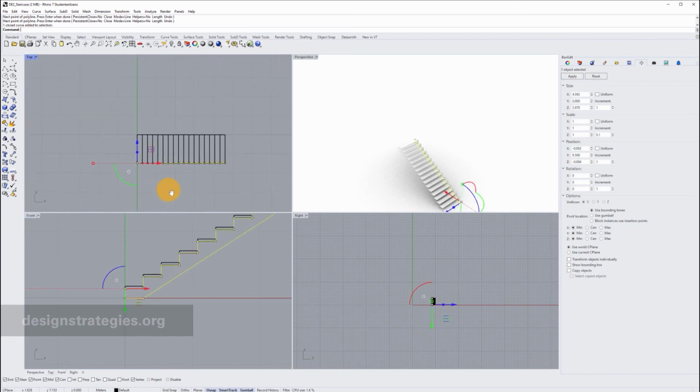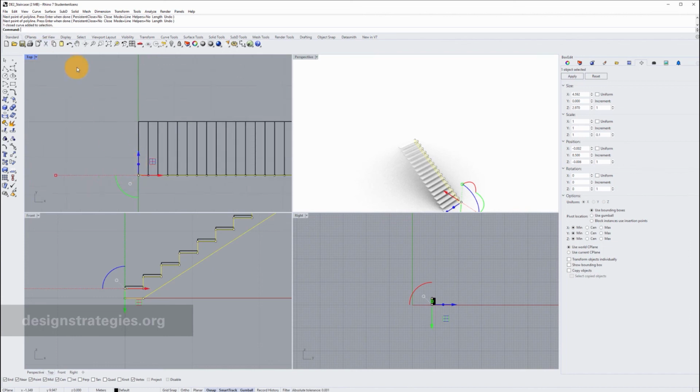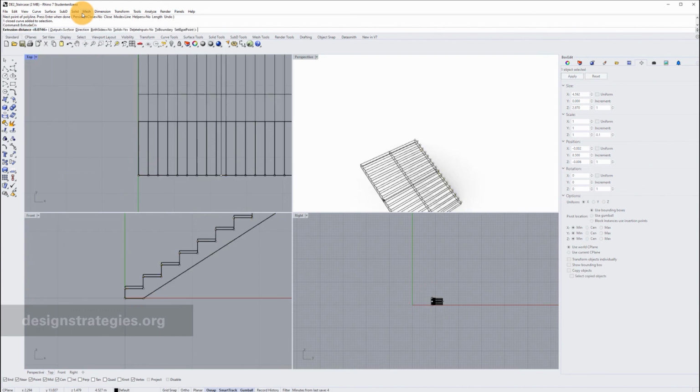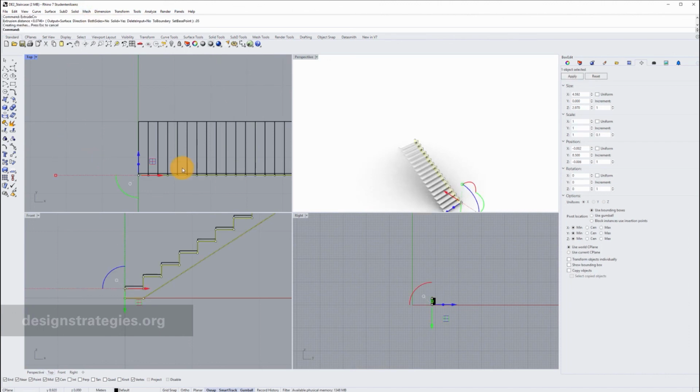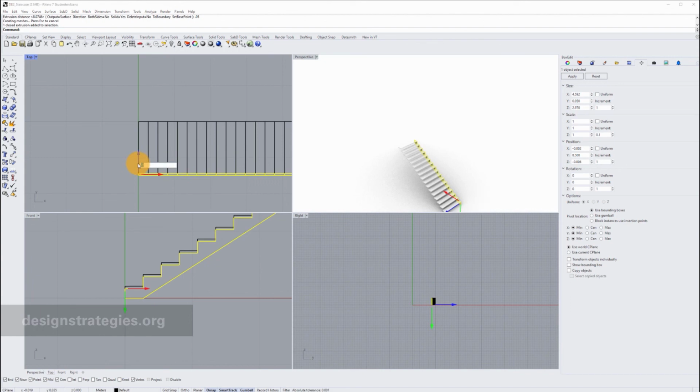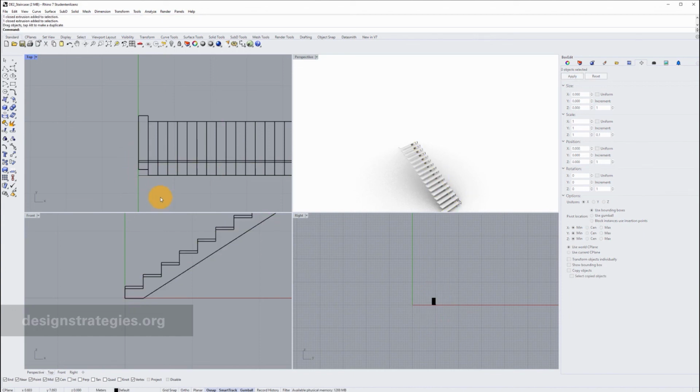And this one I just extrude, for example, or I just also use the gumball, which is also possible. Just say extrude, and I extrude curve to 0.05 centimeters. And now I have an element like this. I just move this also up to 20 centimeters, something like this. And it definitely makes sense to have a second one of this.